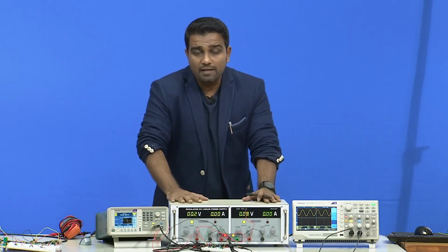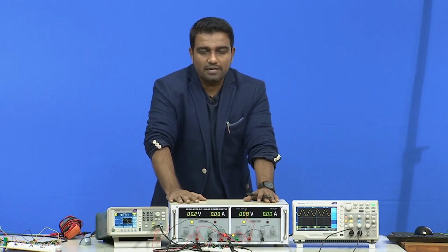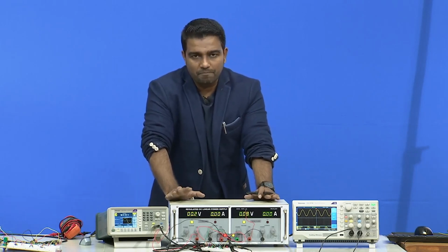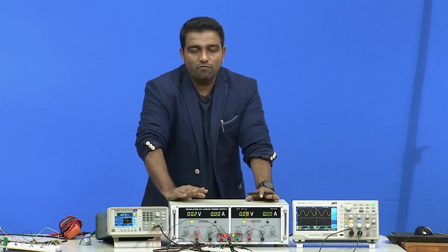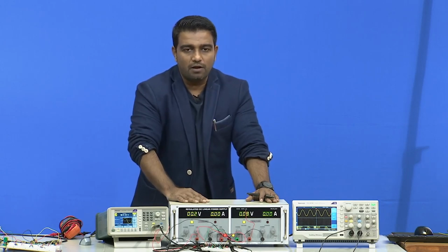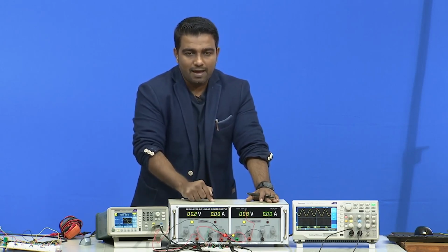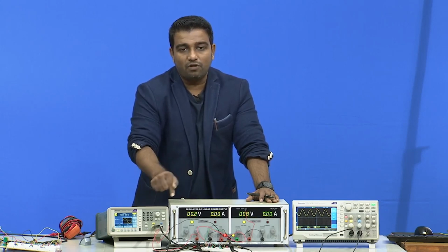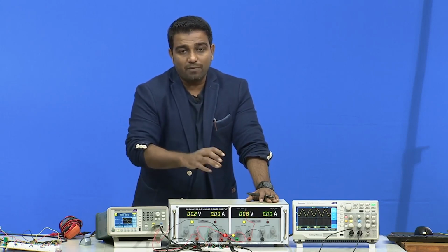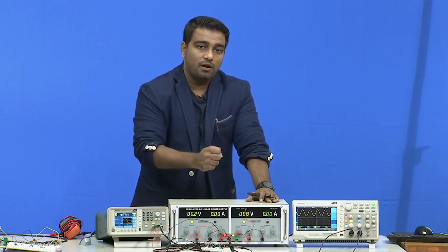The idea is that you have the 230 volts AC and you have to convert this AC to DC. Then you need to first use a step down transformer, which is within this DC power supply, and to that step down transformer you connect a rectifier circuit, and that will give you the final DC output. So, from AC to DC the rectifier is an extremely important circuit.